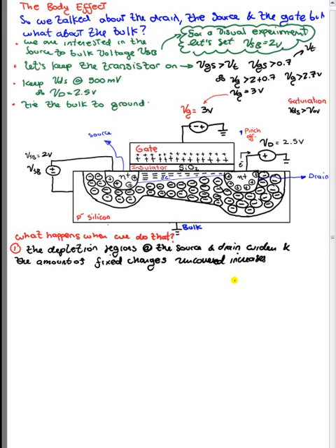Why? Well, we have the drain voltage, which is now higher, and the source voltage itself is now higher too, right? That means that you're pulling all these electrons from the N+ materials in both terminals, and then you end up with a whole bunch of positive fixed charges on this side, and the other side as well. So you increase the width of the depletion region.